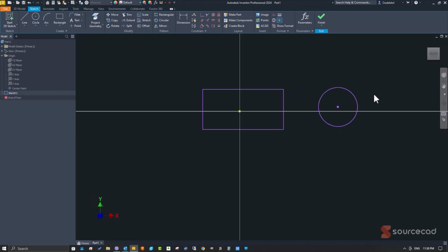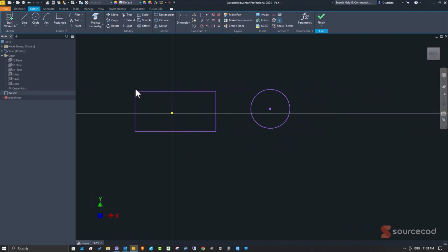And then let's go through and, instead of drawing lines to make a square, we can look at this one right here. You draw a top corner, and again I can use my tab key to go between the height and the length, or I can just place it. You might notice it gives me all the constraints and everything. Now if I hit OK, and if you now look at these, these are purple lines.